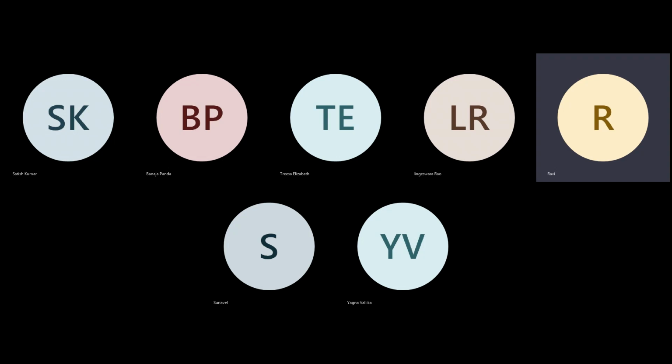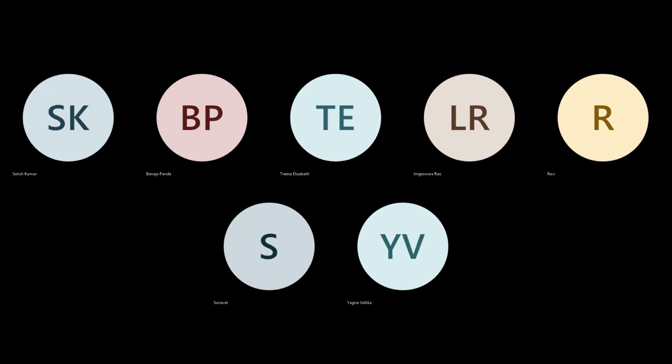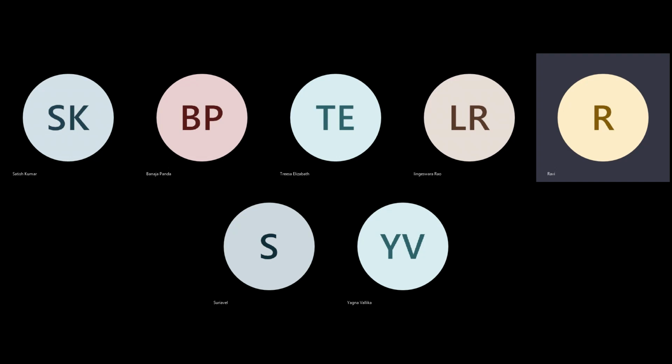If your maximum drive distance is about 200 or 300 micron, you cannot have more than 3 macros side by side, because after that you have to leave space for logic. This should be very clear to you: how many macros can I abut before I place the logic? One macro, the pins are facing. After that, two macros means 100, 100, 200. So this pin can then travel 200 before it reaches the first buffer.